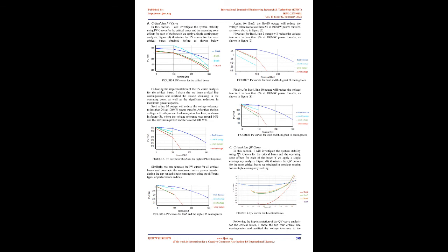B. N-1 AC contingency analysis results. By applying N-1 contingency analysis using the AC power flow analysis, as illustrated in Appendix 2, the performance indices were calculated separately for each case, as shown below in Table 4. Using AC power flow, again line 10 has the highest power flow performance index, indicating that this line is the most critical contingency in the system with 6 overloads. Line 10 outage has the largest PI equals 13.6, then line 1 outage which overloads 2, then line 3 outage with 1 overload, and last line 2 with 1 overload also.